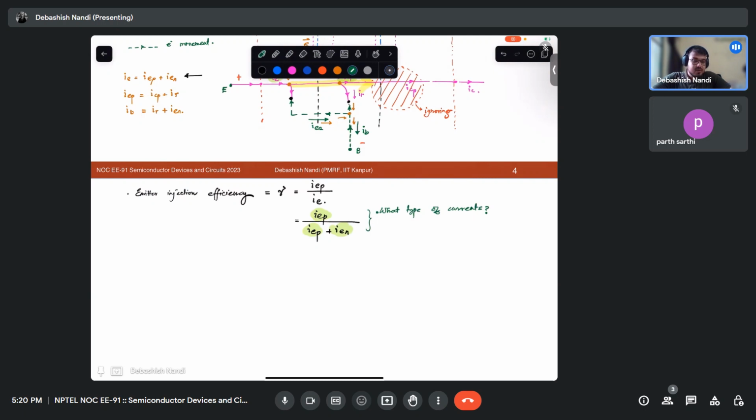So I have only one person. Parts are three. Diffusion and drift. So there are two types of current, right? Drift and diffusion. So what is the major current mechanism in a PN junction under forward bias? Drift... Are you sure? Sorry, no, diffusion. Minority carrier diffusion, right? Yes, sir. That's why there is a current.